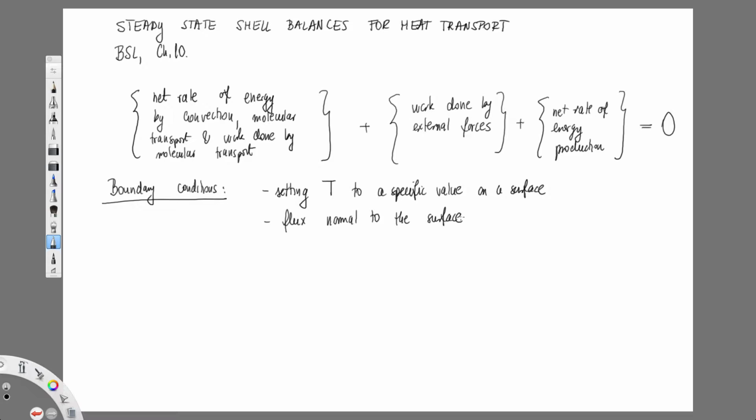And then I also have to look at the boundaries between different materials. So at boundaries between different materials, this is where we will have to look into the thermal conductivity of the material. Essentially, if I have two similar types of materials in contact, I can assume that my temperature is continuous across that contact, even if I have slight differences in the rate that the materials transfer heat.